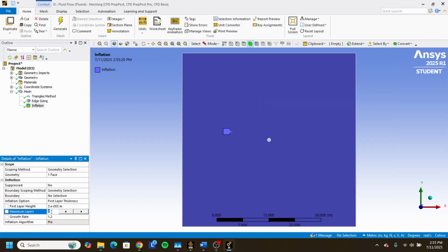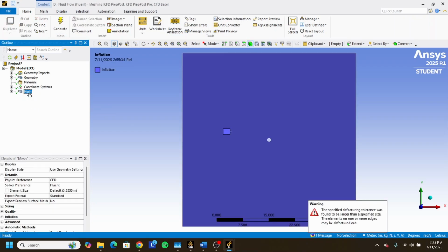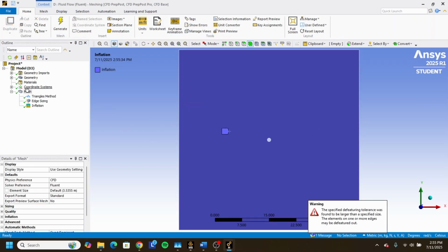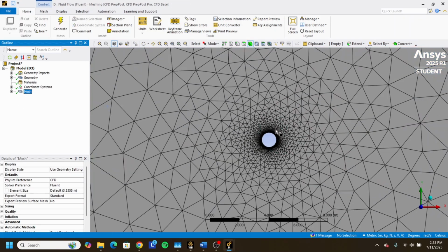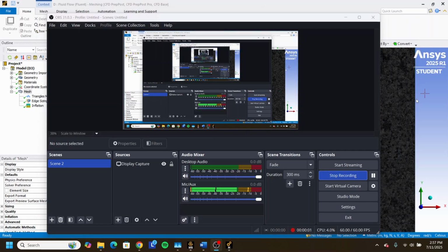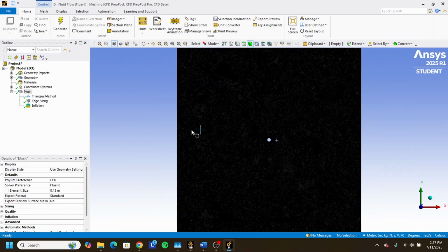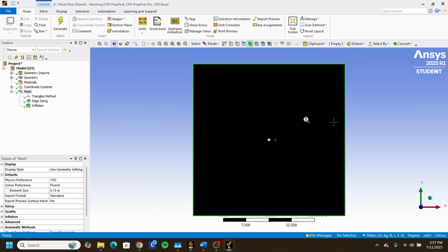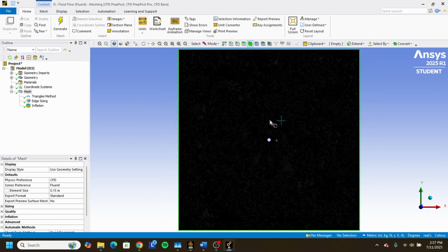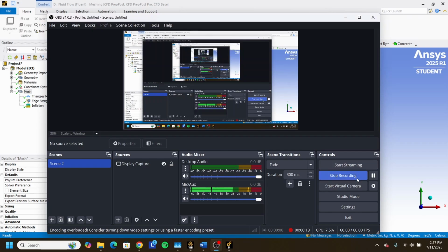Little edit. I forgot to set the maximum layers to 65 actually. So now it should look better. Okay, so this will be the last add-on segment for real this time. I just changed the meshing. Go to mesh, and then you change this element size to 0.15 meters. Click generate. It'll take a while, but it should come as this big black block, and that should be the official end of the meshing segment now.